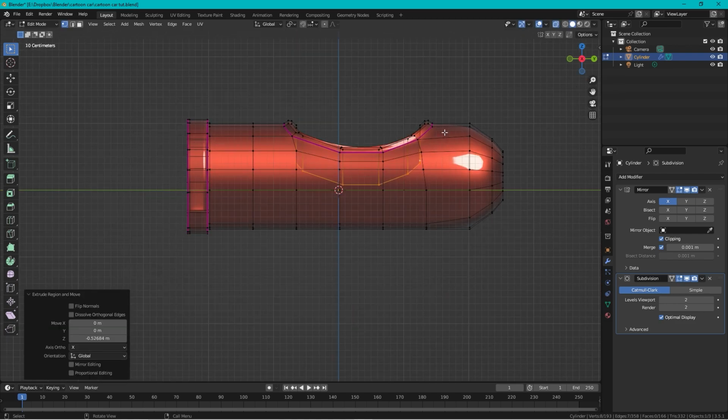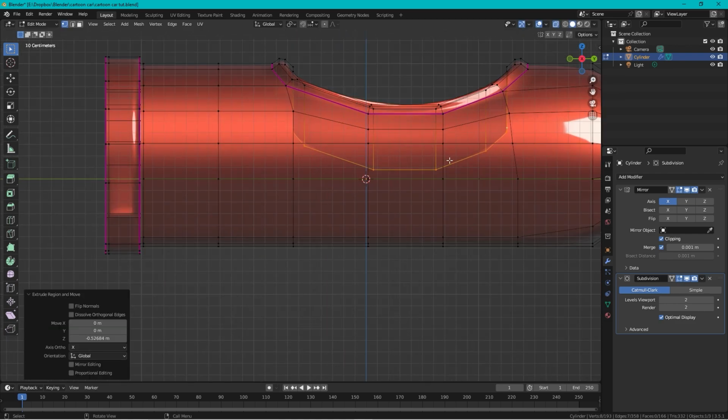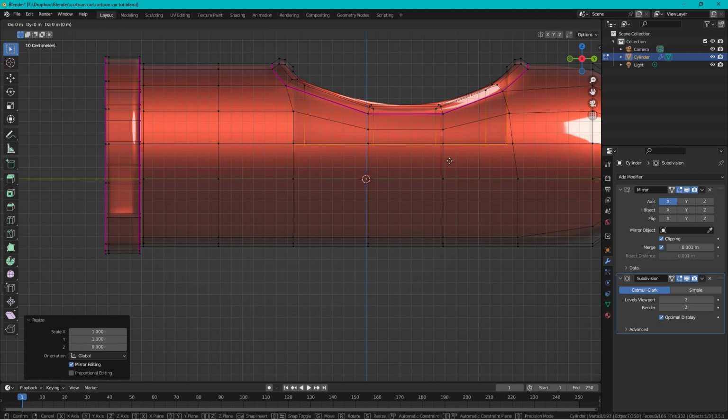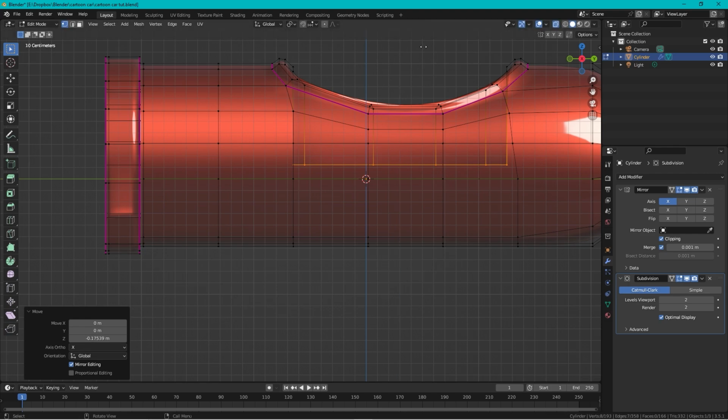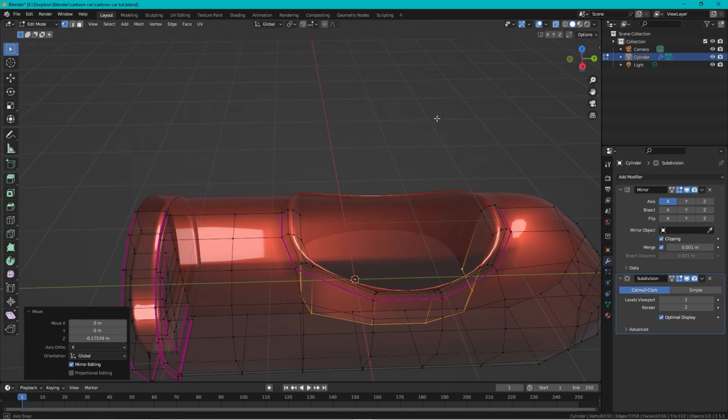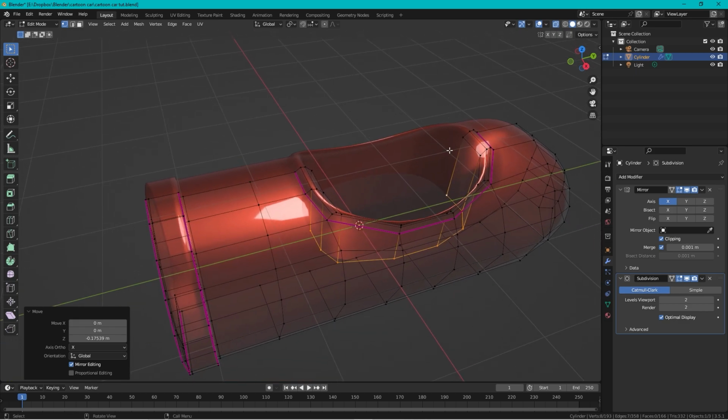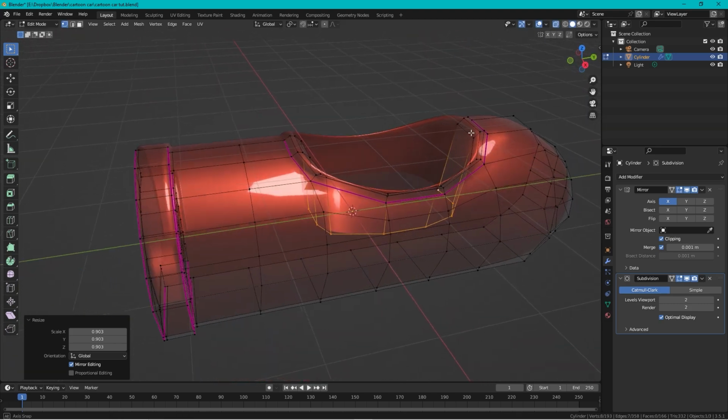But I want somewhere to sit, and I want this to be in line, so let's press S for scale, and I want to scale in Z, and I want to make a straight line in the same plane, so let's press 0. Great, left click and press G to move this down, and Z, drag it down. I think the chairs should start here. Yeah, and I think we should scale everything inwards a little bit. So S, yep, something like that.